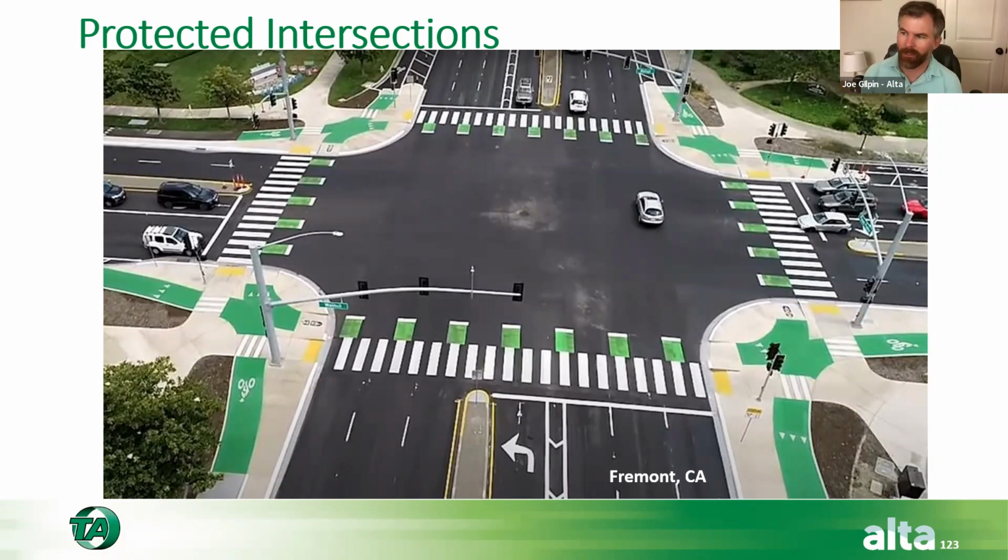There is some research underway right now with FHWA to try to address some of the accessibility issues, because PROWAG doesn't deal with this level bikeway with a sidewalk. Now, if you can get some type of elevation difference between the two, at least where they're adjacent to each other, that can provide that level of delineation, some short curving, keeping pedestrians basically in their pedestrian space and keeping bicyclists in their bicycle space. Those are different ways you can do that. It can get a little tricky from a drainage perspective, other types of facilities there.